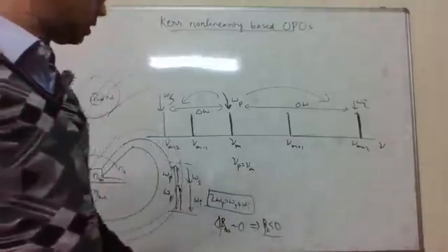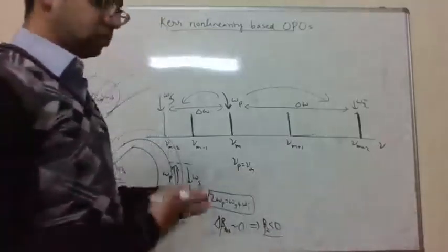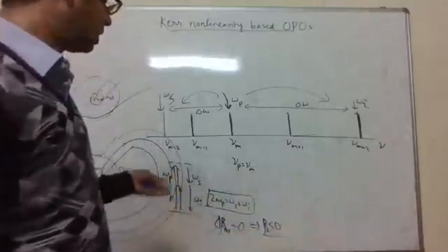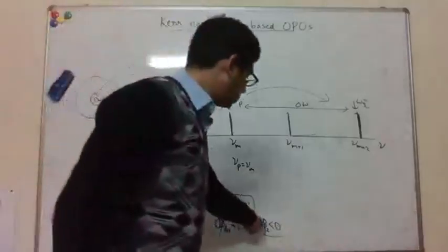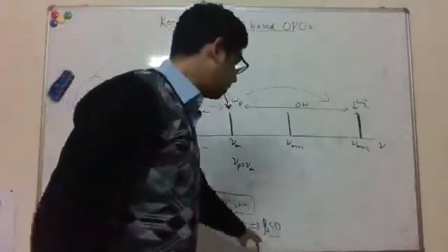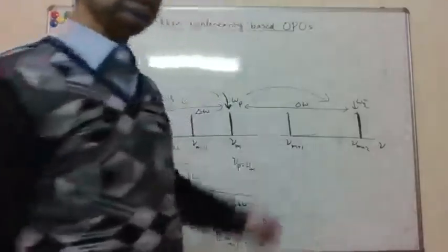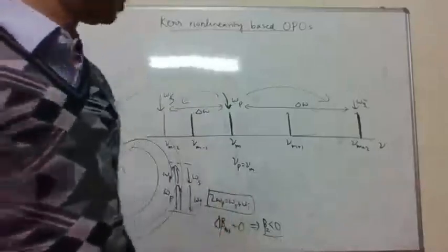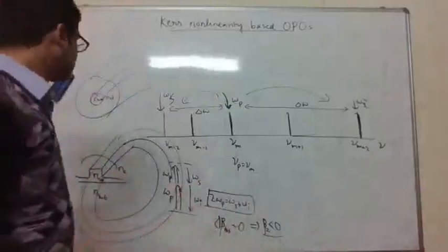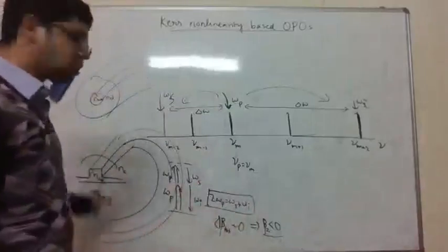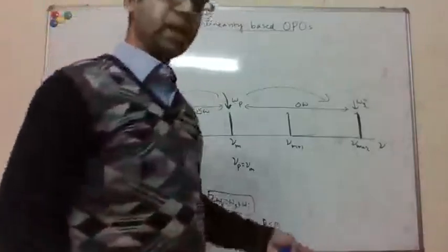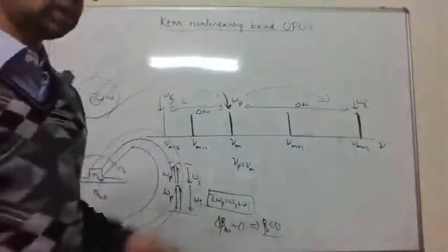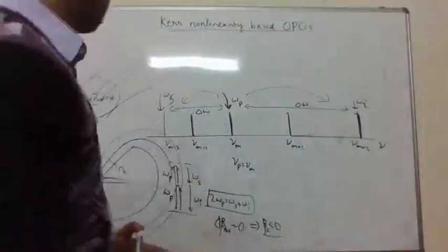So when you plot these refractive indices versus wavelength, in general you will get some beta 2 and even higher orders of beta also, right? You can try to design your waveguide with materials and cross section such that you get beta 2 close to 0 at the particular wavelength you are interested in. That's dispersion engineering.